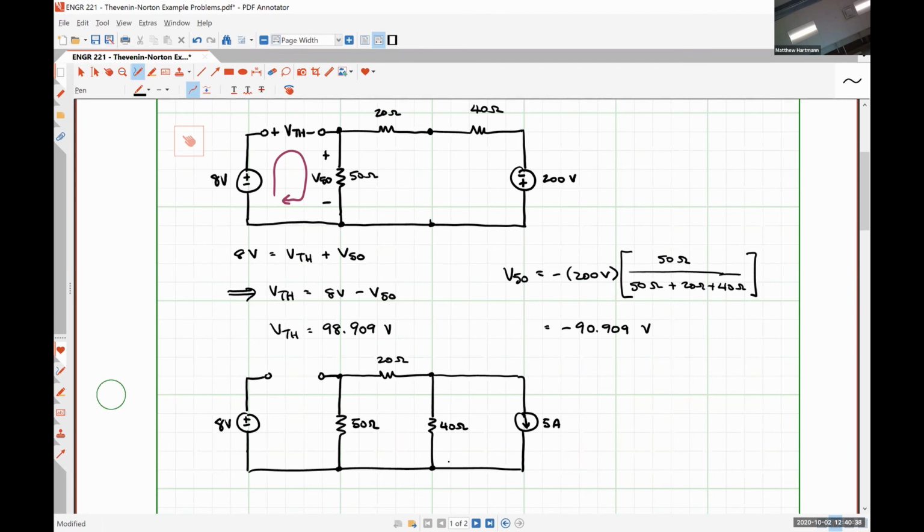So how do I turn a voltage source off? For a voltage source to be off, we want the voltage to be 0 and any amount of current that needs to flow through it can. So it'll be a short circuit. And how do we turn off a current source? That's the open circuit, which is the same as me just plucking it out.